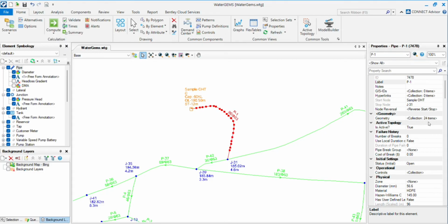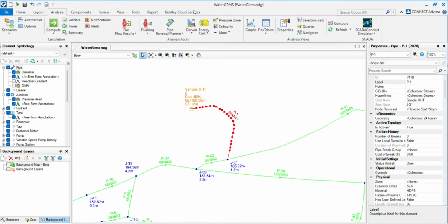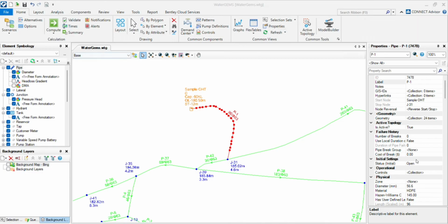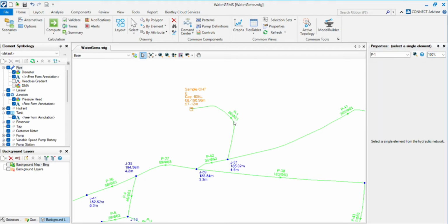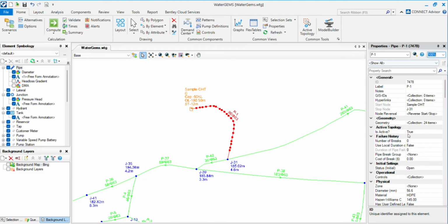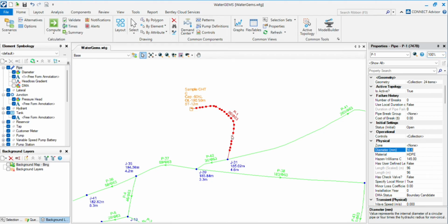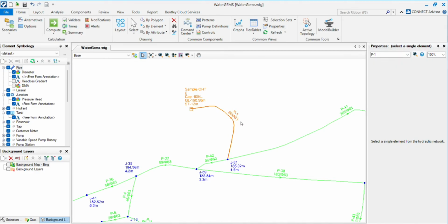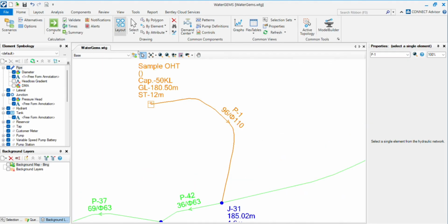this is the property table. You can get the property table, we have the property table in the home button. This is property. You can click on that or double click on the pipe or any element. You will get the property table. So we have to put an internal diameter of, let's consider 110, 97.5. Okay, click on refresh. You will get the 110 pipeline.